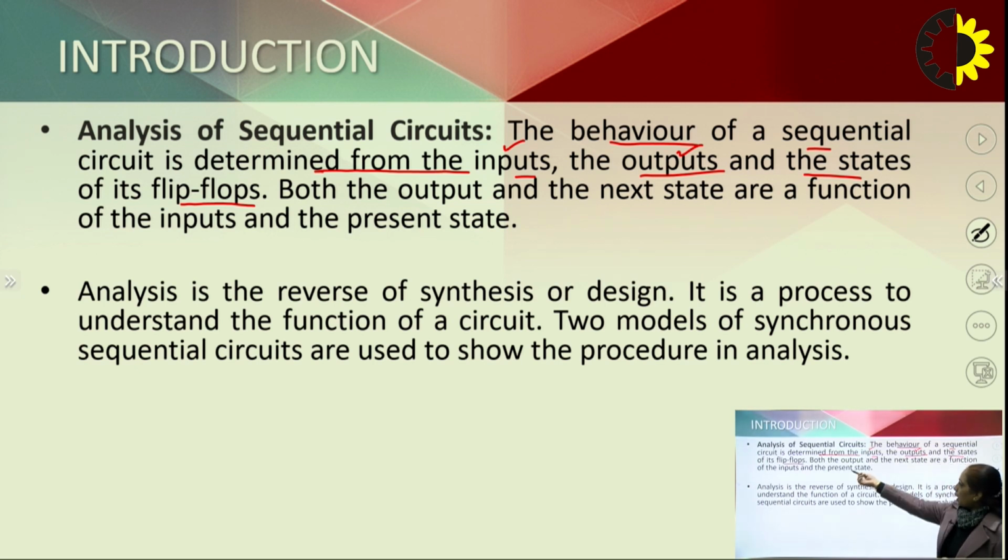So both the output and the next state are the function of the inputs and the present state, right? We have also seen in flip-flops, when we analyze the flip-flop, the next state output is the function of your previous output as well as the input, right? So analysis is the reverse of synthesis or design. It is a process to understand the function of a circuit, and there are two modes of synchronous sequential circuits.